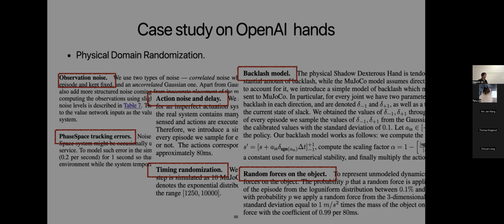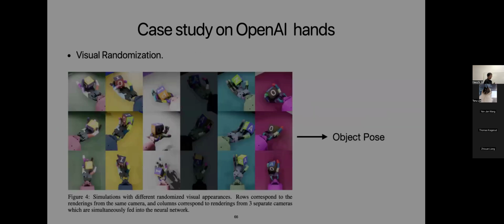So that's all from the physical and observational side. There is another aspect which we briefly talked about: simulation images are really different from real-world images, and if we directly train a policy taking RGB images, that's unlikely to work. So what we rely on for all this sim-to-real work is finding something we call abstractions. You find some abstraction that, although the RGB images are not the same between sim and real, we hope can be the same from sim to real.